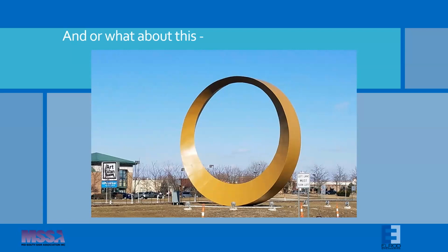To ensure that we designed a safe structure, we utilized a 3D finite element analysis software package to model and check to ensure that all the structural components were strong and that the deflection under full wind loading conditions was minimal. It was important that the fit and finish of these panels be of high priority because you didn't want the sign or the structure deflecting and creating gaps in those panels.